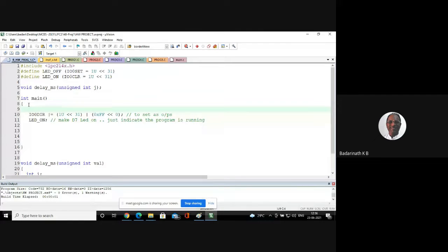Check whether unsigned character is sufficient for this purpose. Always try with unsigned character first. If it is sufficient, go with unsigned character. If it's not possible, then only go for an integer. If that is not possible, with 2 bytes, let's say, then only go for a long integer. Always think like that and move forward. Then you conserve a lot of space in the SRAM, so that as the project becomes bigger, you have enough memory to handle a lot of other work.